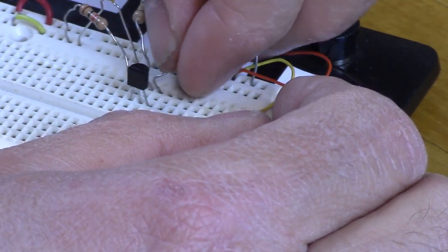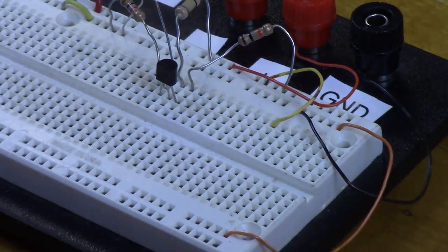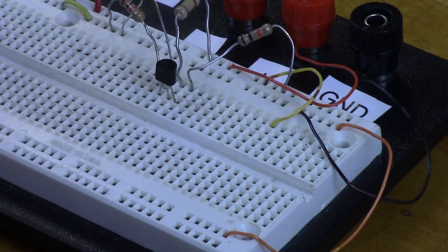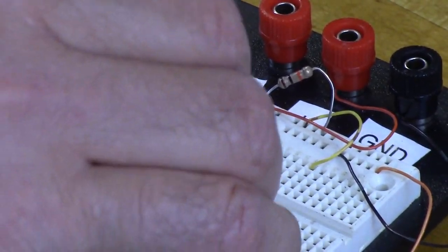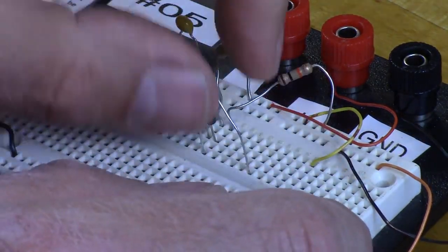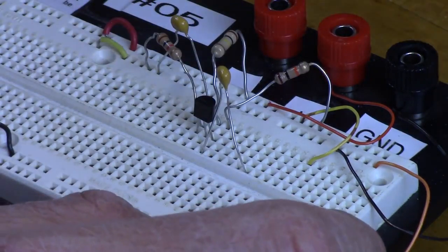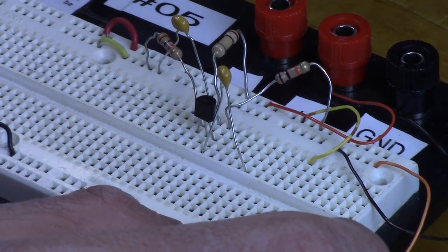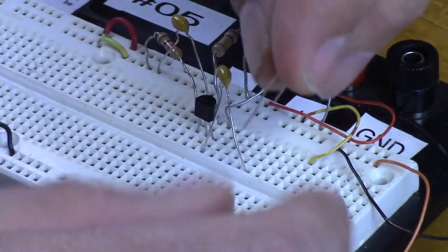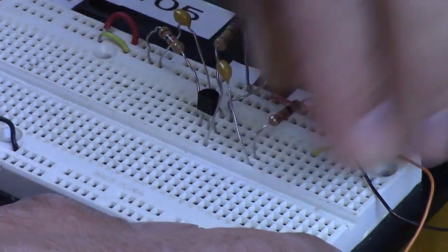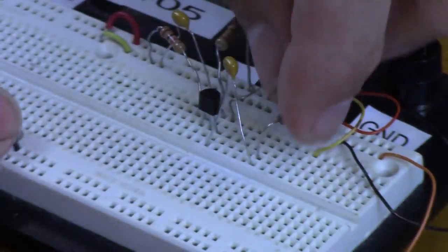Okay, so here's our RC going up high, and then we're going to go through capacitor C2 from the collector off to the side. And then we're going to have our other 10K resistor being our RL. That's going to go from C2 to ground. Over there, that's in place.